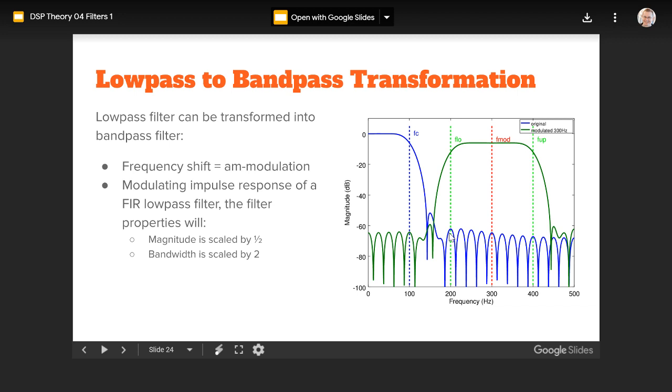So if you have a signal spectrum like, well, let's make it like this, for example, an ideal case of signal spectrum, and you want to transfer that spectrum into some other place, symmetrical of course, with the information on a carrier, so you would actually have, if that is x of t, this would be x of t times cosine 2 pi fm times t.